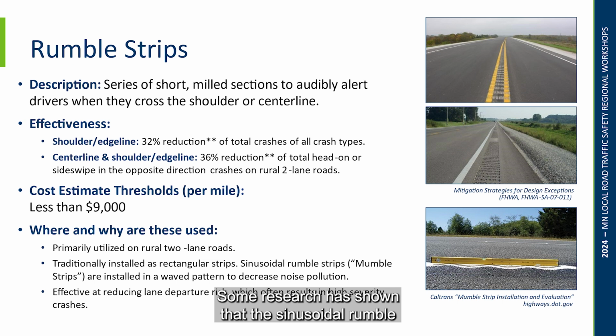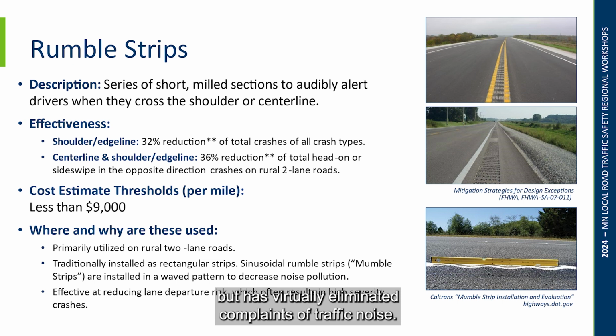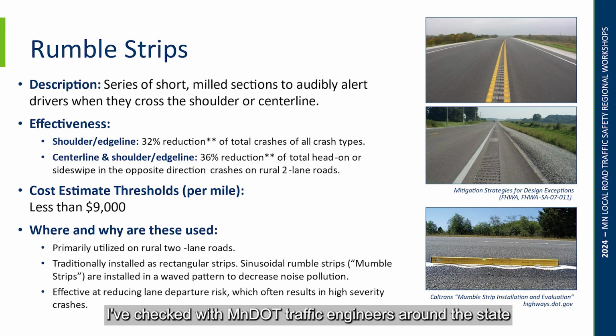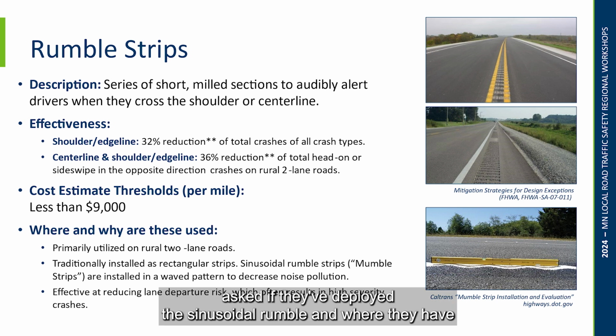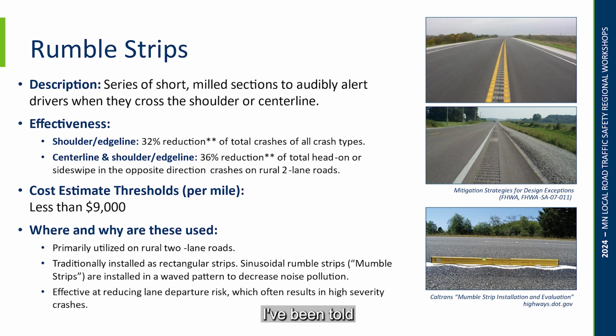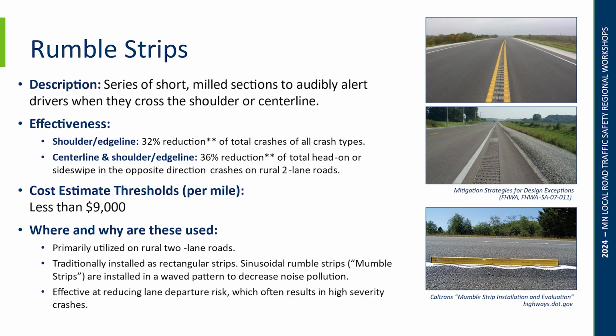Research has shown that the sinusoidal rumble has similar crash reduction capabilities similar to the vertical cut rumble, but has virtually eliminated complaints of traffic noise. I've checked with MnDOT traffic engineers around the state, asked if they've deployed the sinusoidal rumble, and where they have, if they've had any noise complaints. And anecdotally, I've been told there have been zero noise complaints associated with the sinusoidal rumble.